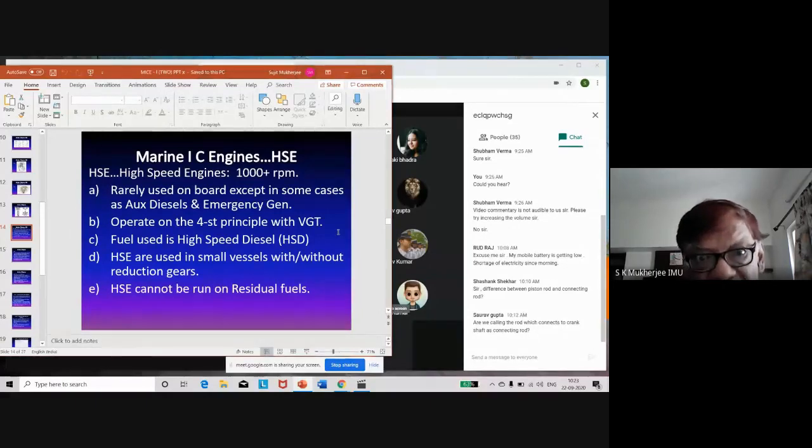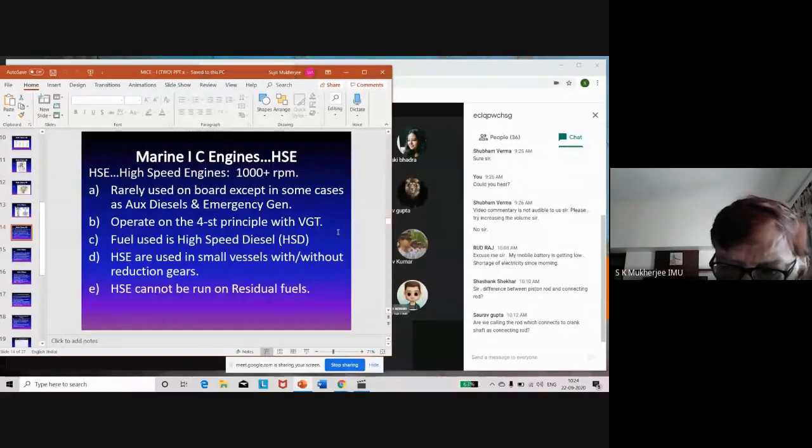So the turbine will become much faster in its rotation if you narrow the passage of the exhaust gases leading to the turbine. The moment you have an increased speed of the turbine, you automatically deliver more air to the engine. So variable geometry turbocharging is an arrangement which reduces the nozzle to the turbine blades, wherein the flow of gases is directed.